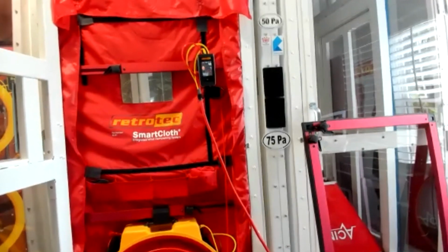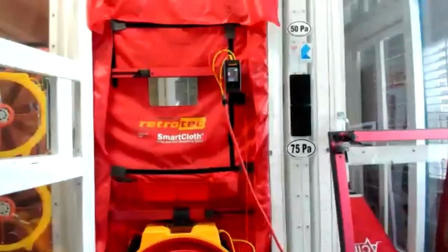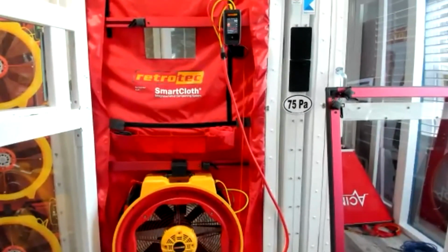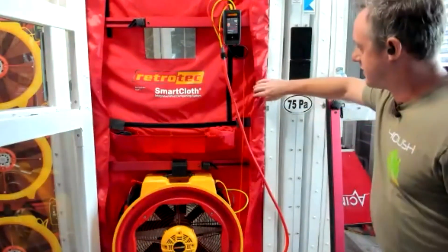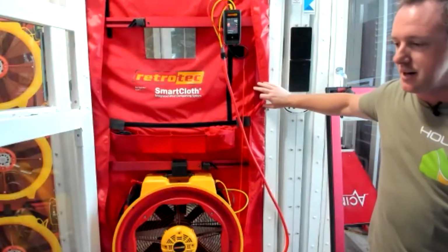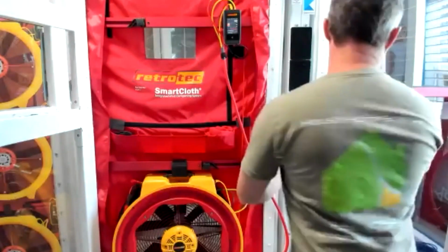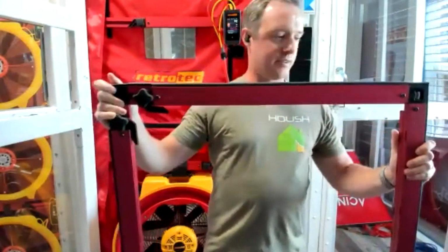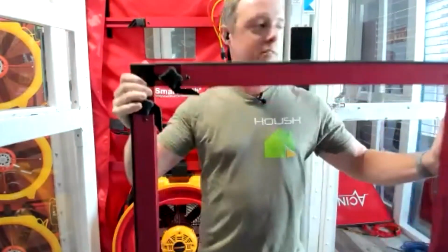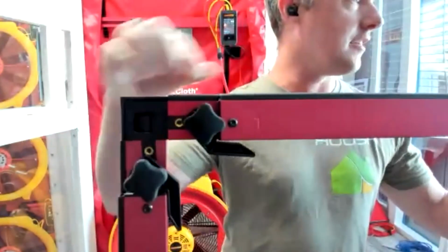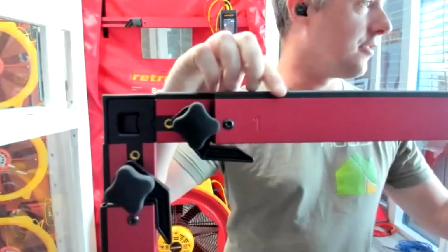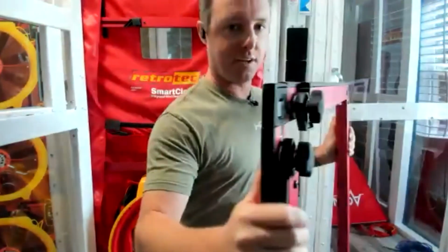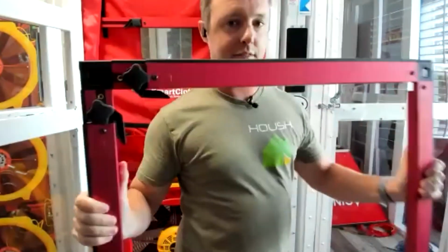So obviously you can see that this blower door is already installed, but let's talk a little bit about how that comes together. What you see here is an aluminum frame that comes in 4 pieces. So when you have it assembled, it looks like this. I think you can see. All you do is match up the numbers in the corner. So there's a 1, and then there's a 1 here. You just match them up. And there's a rubber seal that goes all the way around the edge, so you get a good tight fit into the doorway.